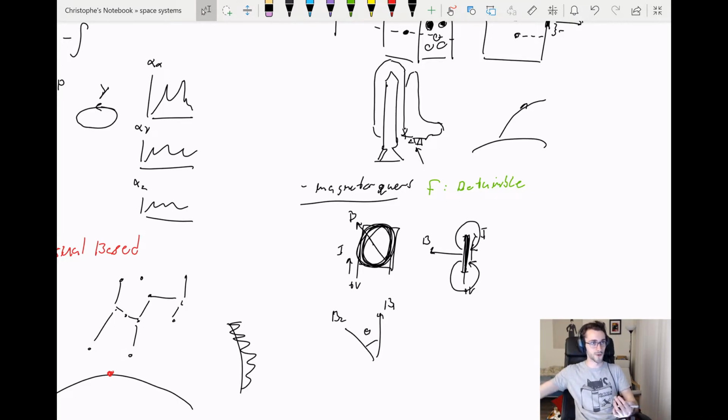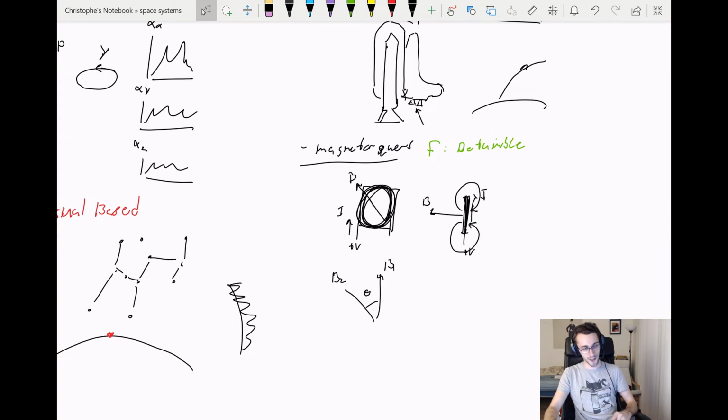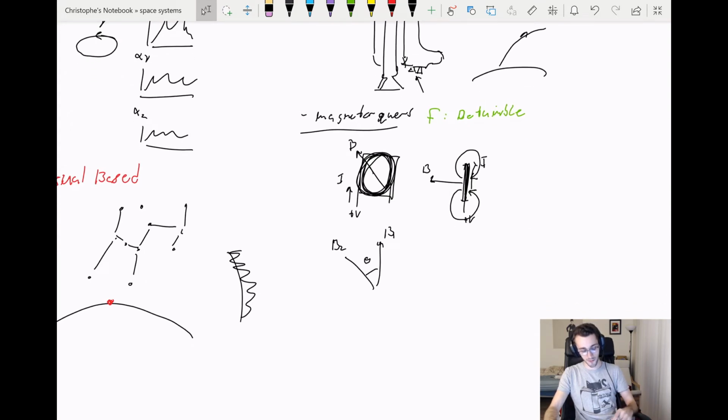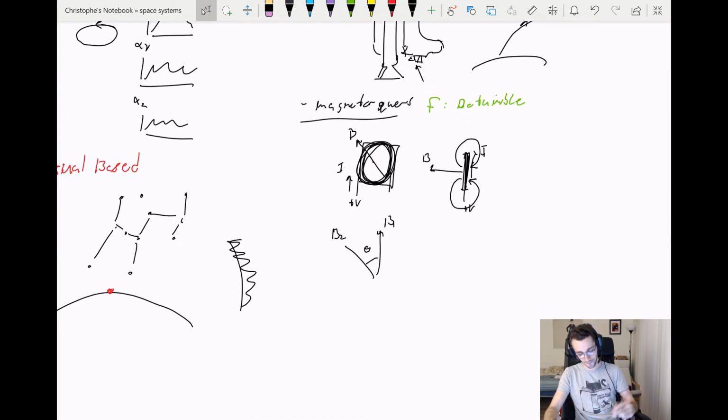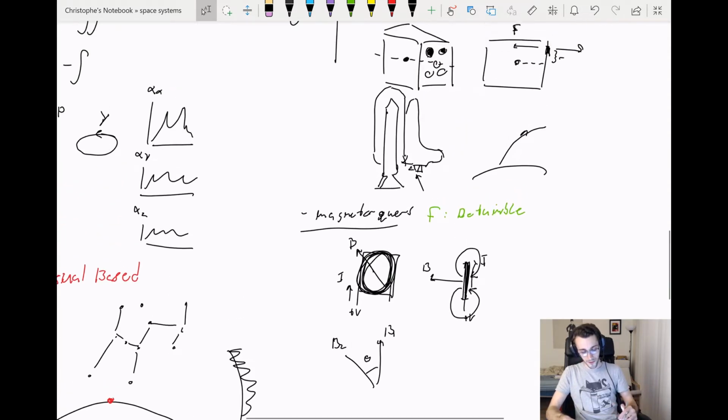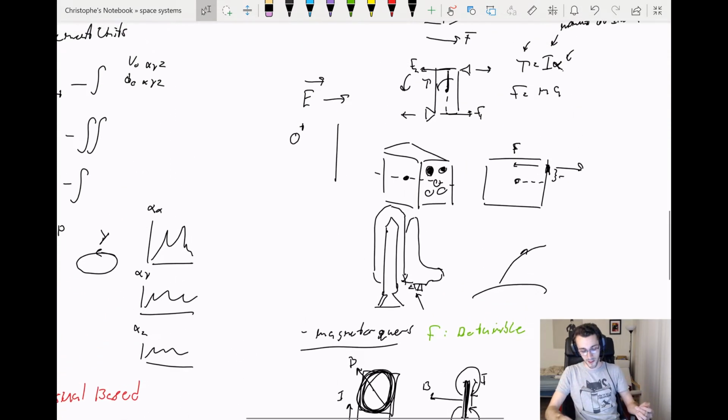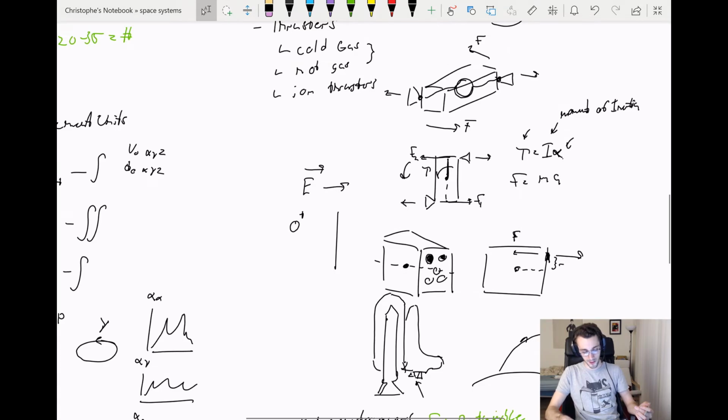If the magnetorquers were the rock concert and the Earth's magnetic field was the whisper, you've got this thing blaring right next to you while you're trying to focus on this thing that's very ephemeral compared to the magnetorquers. So you keep that in mind when you're designing these systems.